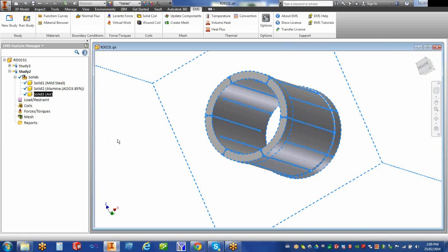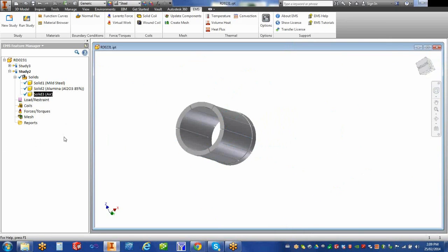All right. So what is different about this? In addition to being fully integrated in Inventor, our electro-thermal solver is also integrated together. Usually some other software vendors make you do the electrical analysis, be it AC or any other type of analysis. Then you have to export the file that has a heat load on the nodes, close the program, open another thermal program, and read in the data and do your thermal analysis. We do it differently.